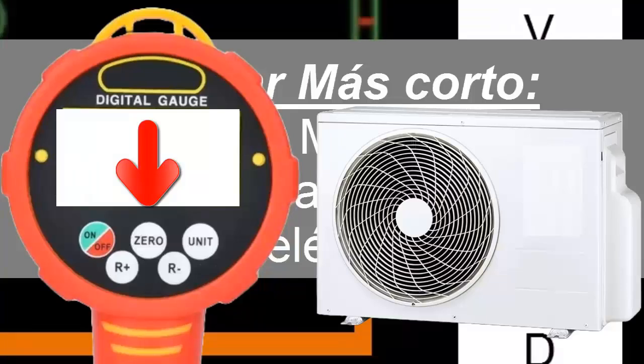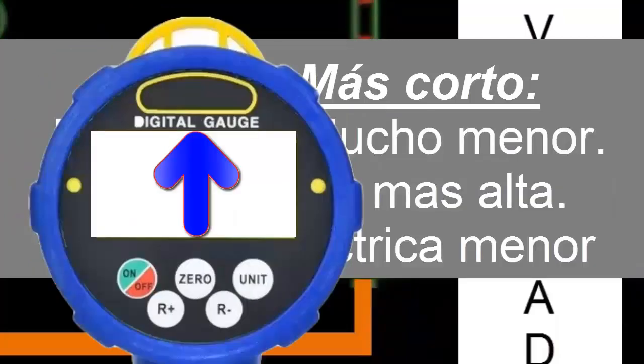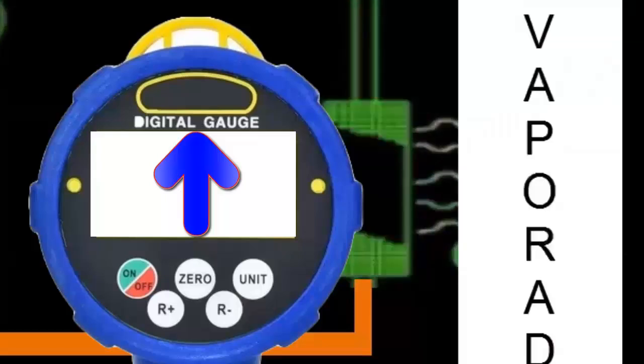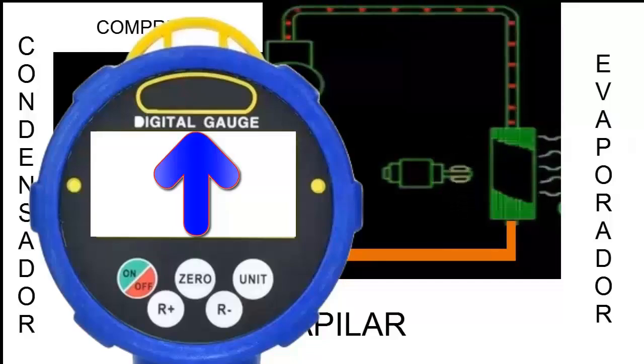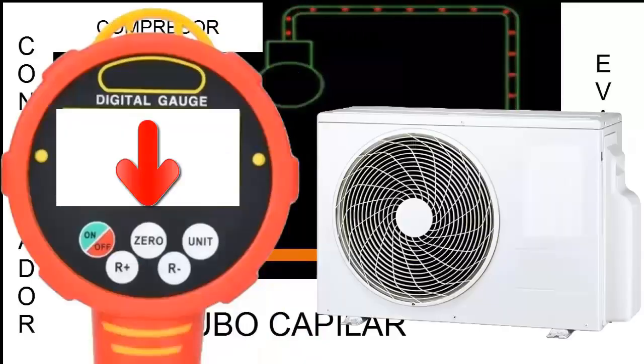For condensation to occur efficiently, a sufficient pressure level is required. Low pressure may also be affected, as more refrigerant reaches the evaporator, which could slightly increase low pressure. However, the most critical effect is on high pressure, which may drop to critical levels, preventing proper condensation and disrupting the refrigeration cycle.